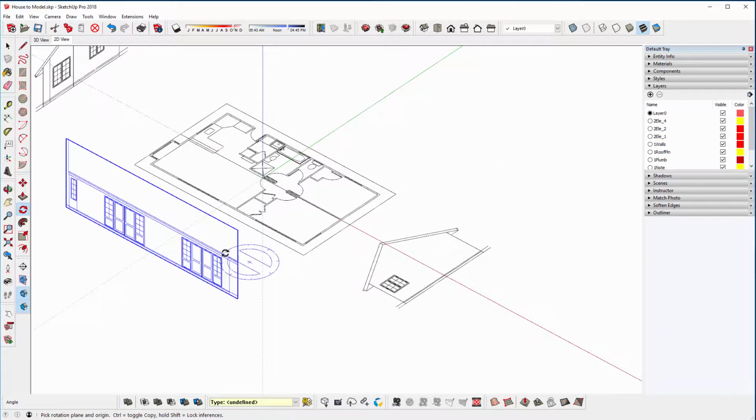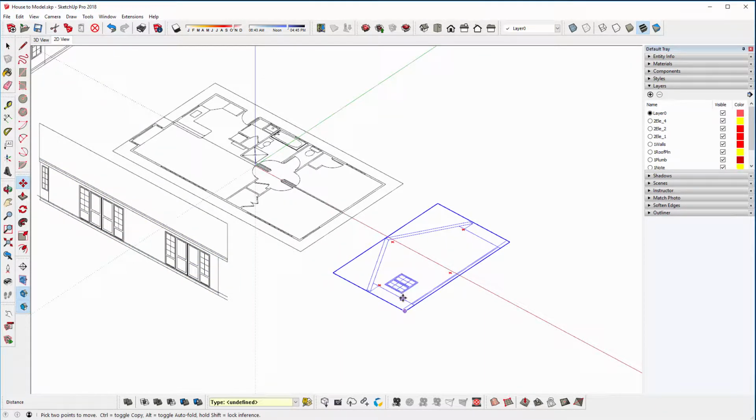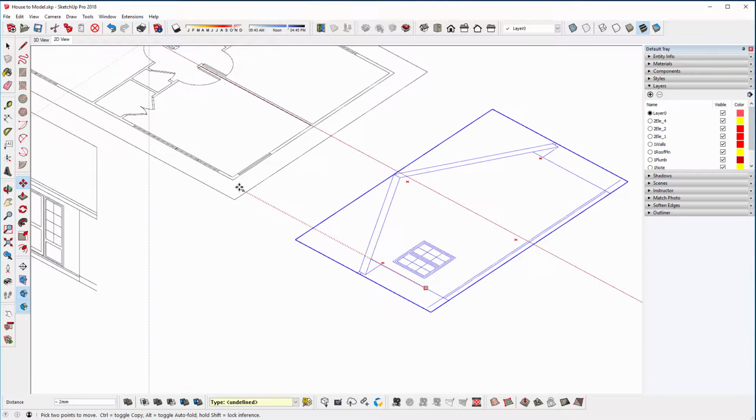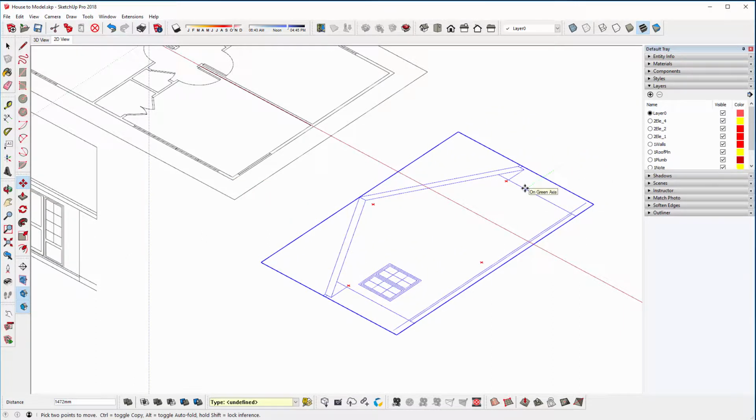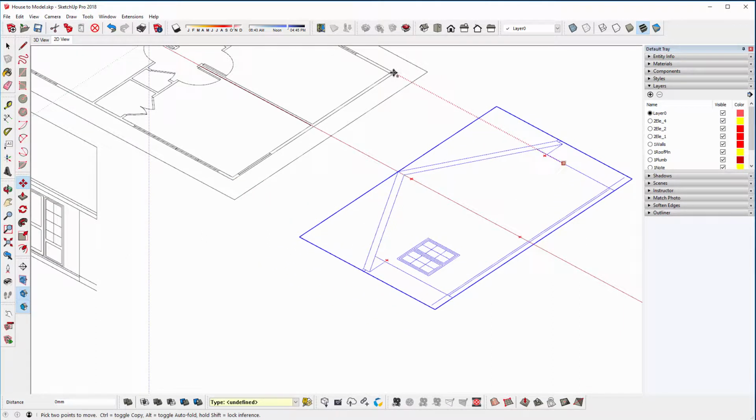Or you can just click once it says 90. So again, click on the elevation, move tool, and we'll click on the edge, left arrow, and then align that to the wall. Double check the other side, click, left arrow, align to the wall. 0 also, so this elevation is good as well. So there just must be an error with that one elevation.